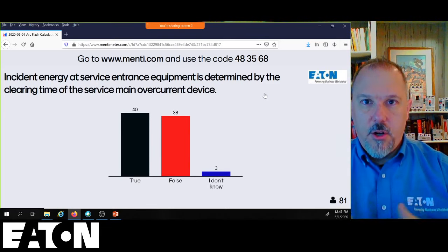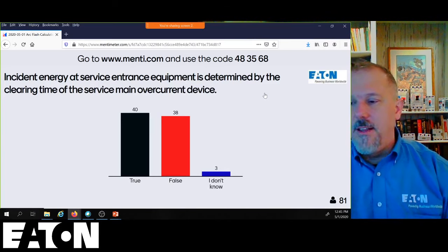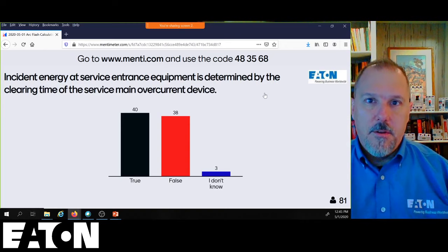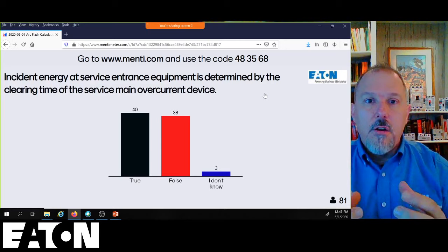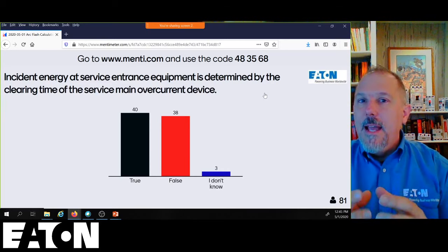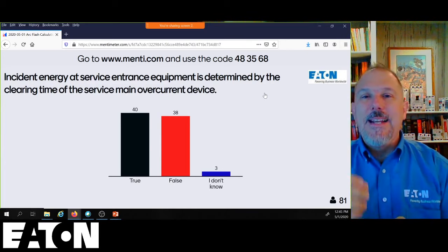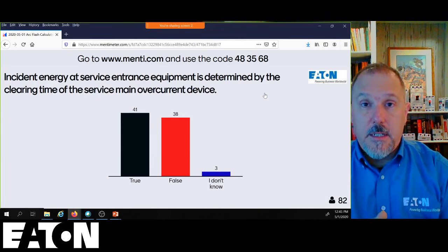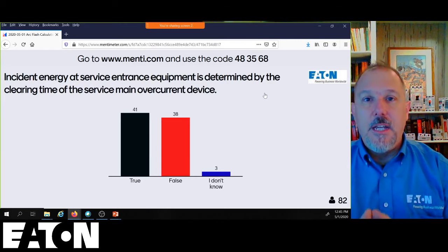When you understand what an arc flash event is, it's that plasma, it's that cloud. I call it the plasma plume, and people make fun of me, but it's a plasma cloud of ionized air, and electricity current flows through air. So what can happen? I'm not going to say it will happen. I'm saying it can happen, and we as engineers, as safety professionals, we have to assume the worst case, and the worst case is you get what they call line side propagation.